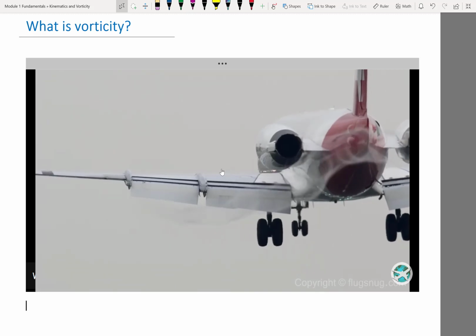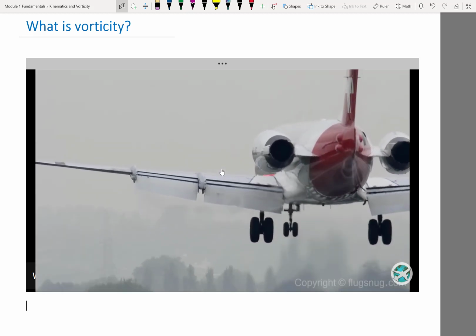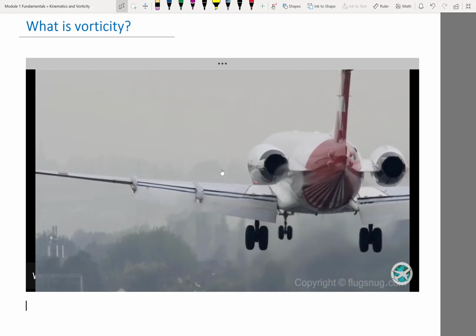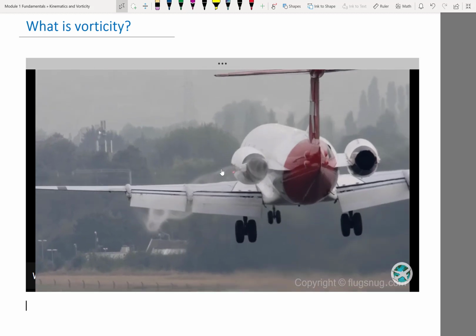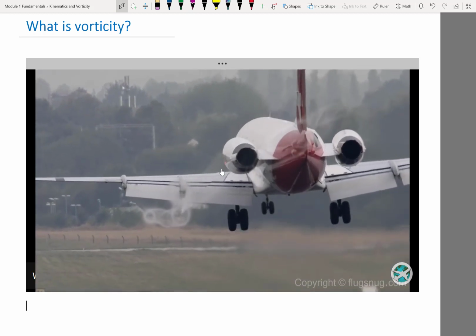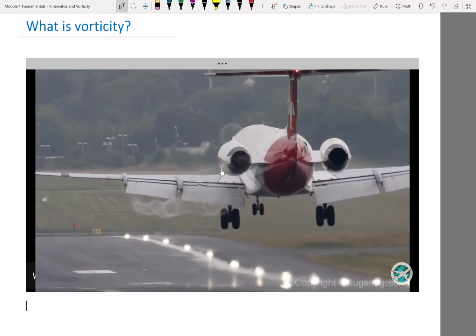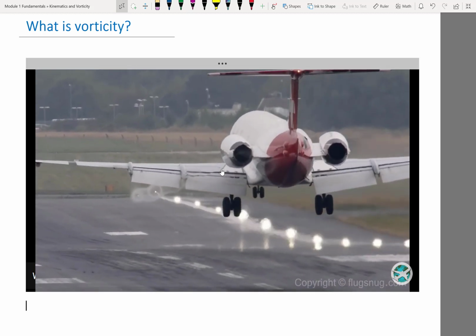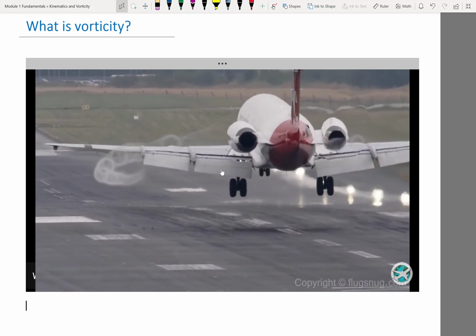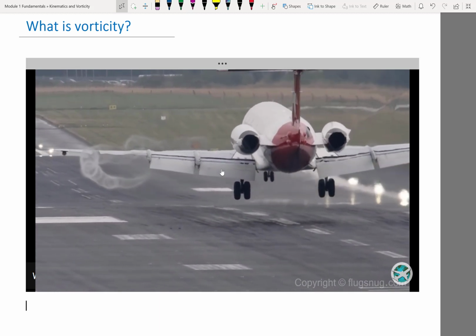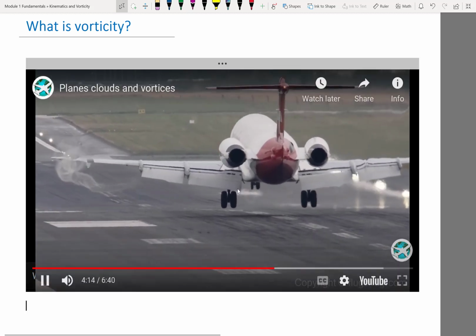Right, so basically this is a case where there is vorticity coming out of here, but there are also large regions of the flow where there is no vorticity, right? And we want to be able to derive, first of all, how would the air move when there is no vorticity around? And two, what equation does vorticity follow? And the third, how does air move around these vorticities?